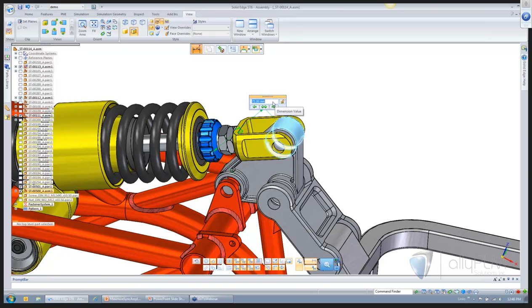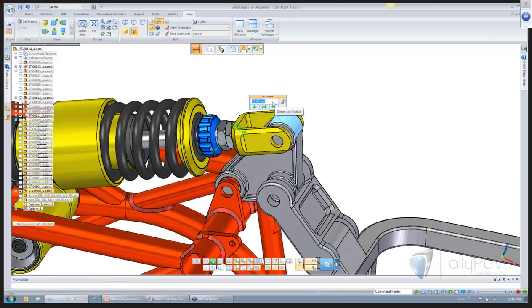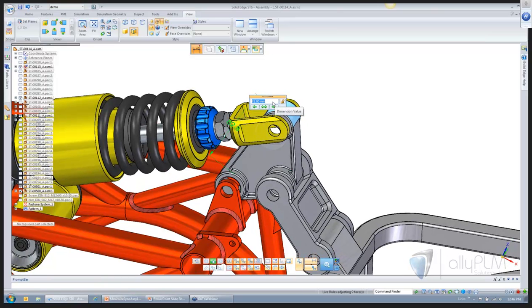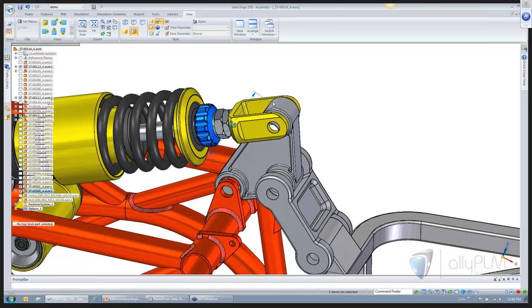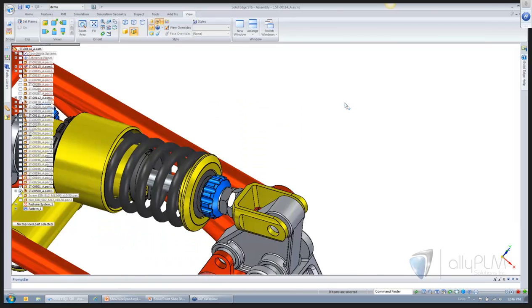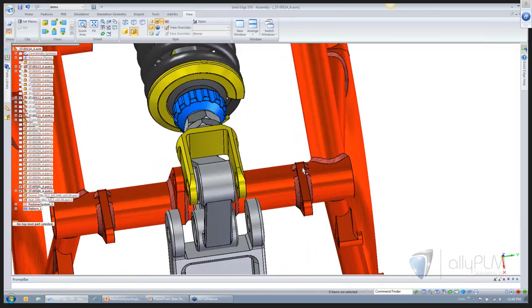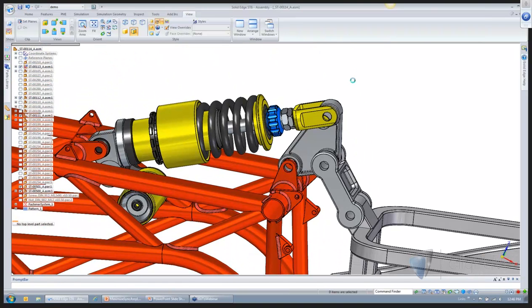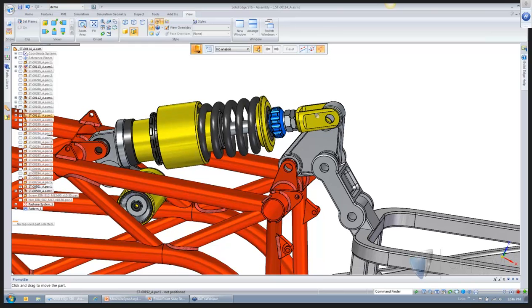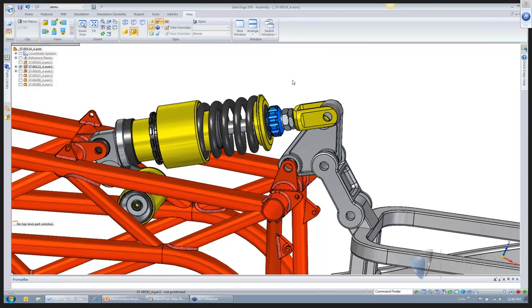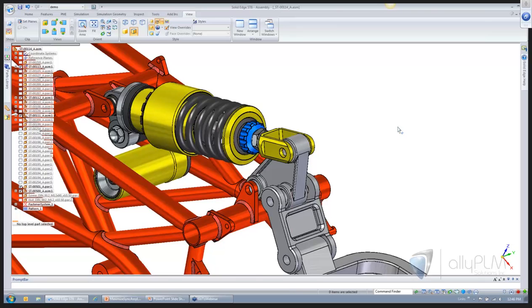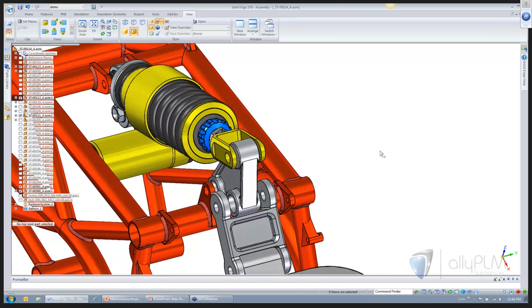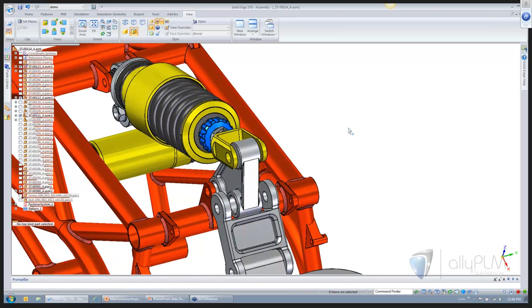So I'm going to drive this thing by the dimension, and I can use my mouse wheel and do a dynamic edit, or I can say that, hey, I know the maximum amount of material I have per my stock is going to be 85 millimeters between those holes. And so we can look at what that did kinematically to the assembly, and did it clear up any type of interference we have. So we still have a kinematic functioning assembly here, but we were able to modify the part at the assembly level and see what impact it had to the kinematic function of the assembly.